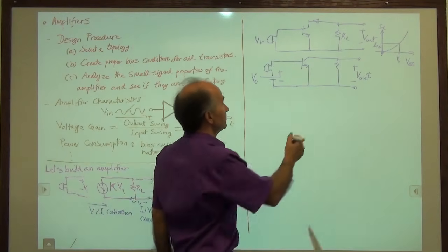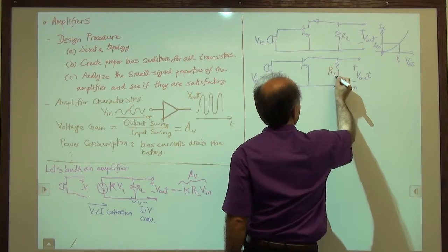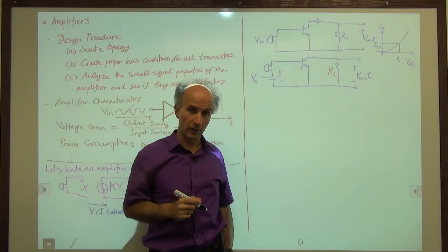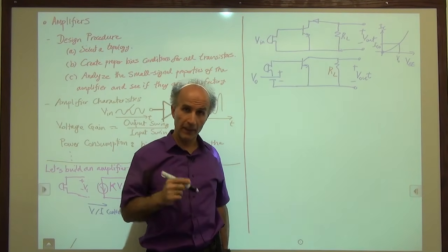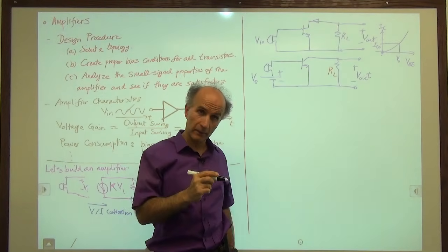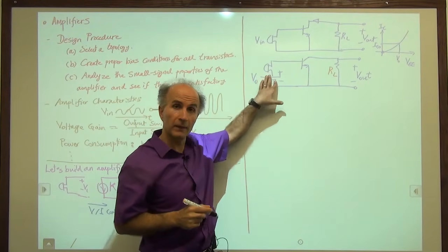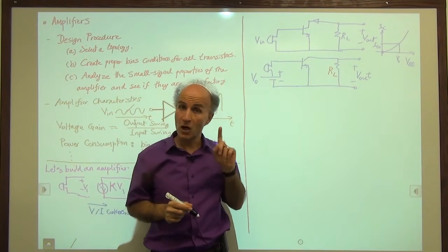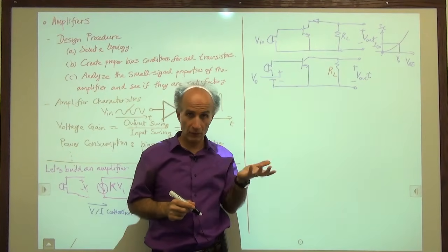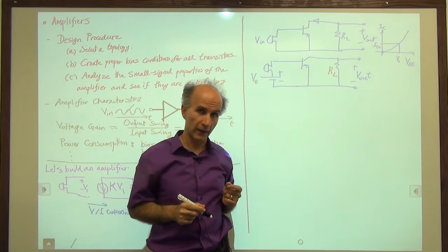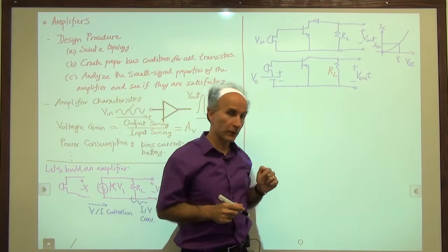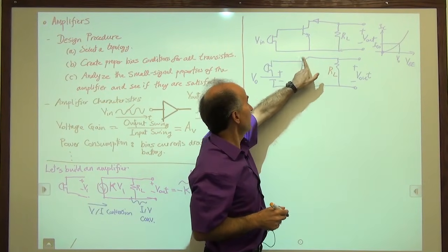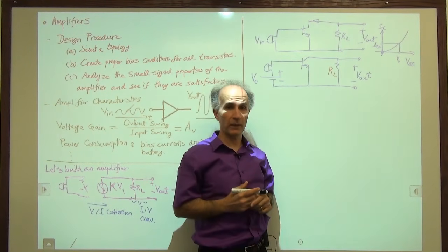Okay, well, remember that a bipolar transistor needs to be in the forward active region, and that requires that the base emitter be forward biased. Sure, we have that. But the collector base must not be forward biased, must have 0 or reverse bias on it. So the question is, with this arrangement, am I sure that the base collector is not forward biased?